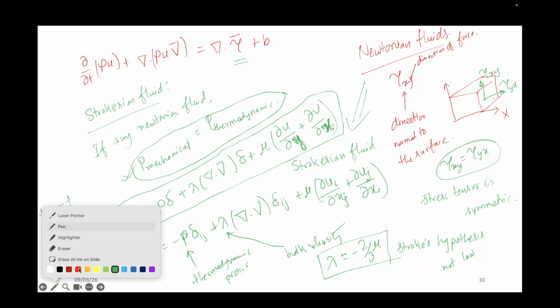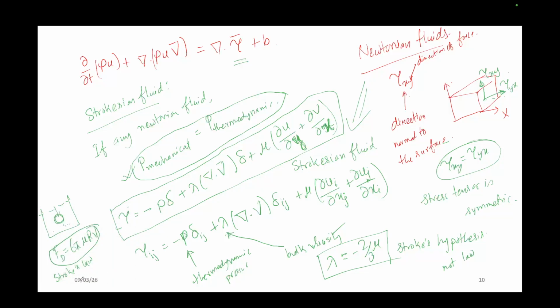I am just putting a few things in this equation so that you can easily understand. In the Navier-Stokes equation, from this Stokesian fluid formula, finally after so much derivation from this part, what they got is minus del P, pressure, plus mu del square V, plus the body force. Body force means rho g. You got it?